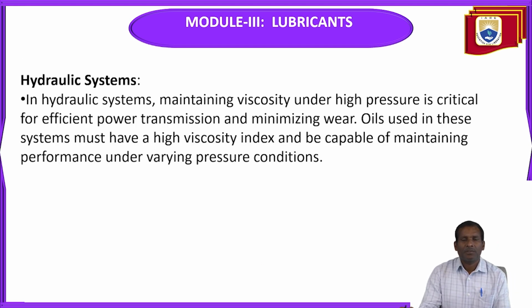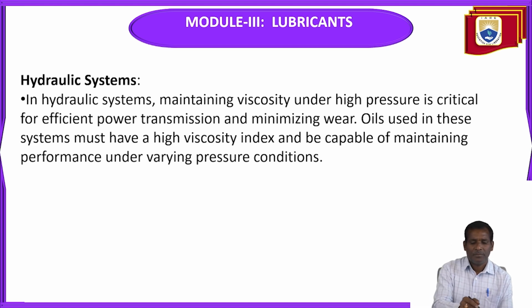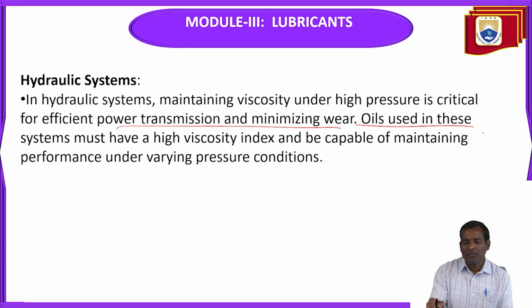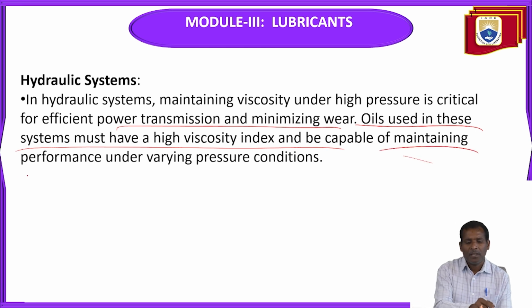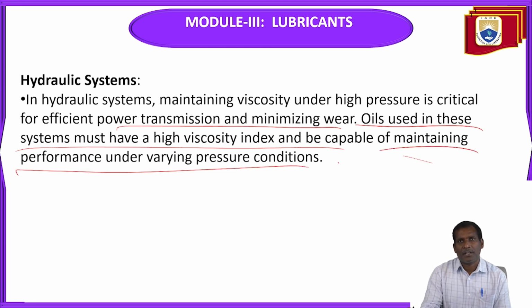Next, hydraulic systems. In hydraulic systems, maintaining viscosity under high pressure is critical for efficient power transmission and minimizing wear. Oils used in these systems must have a high viscosity index and be capable of maintaining performance under varying pressure conditions.